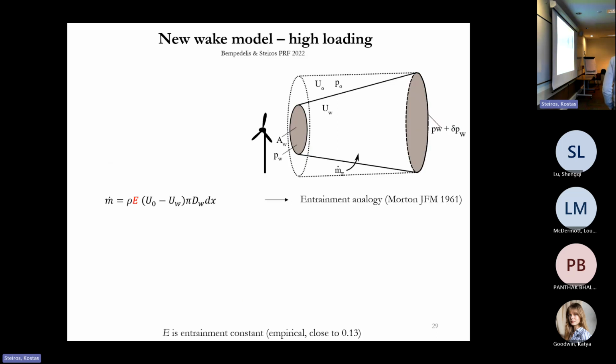All right. So this is something that I did with my colleague last year. The idea of this model is that we have a wind turbine here, and we take a control volume, the one that you can see, bounded by both sides. We're thinking about an axisymmetric problem, and we see the evolution of the wind velocity. This line here separates the wake of the wind turbine, the turbulent region, from the outer flow, where we have the outer velocity, which is unperturbed.